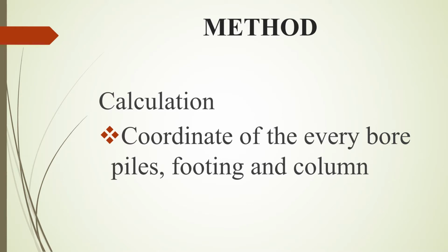Calculation. The coordinates of every bore pile, footing, and column are calculated from the AutoCAD software. Before calculating the coordinates of every structure, make sure the construction plan is superimposed with the survey plan. It is to ensure that the construction plan is in true orientation and position.